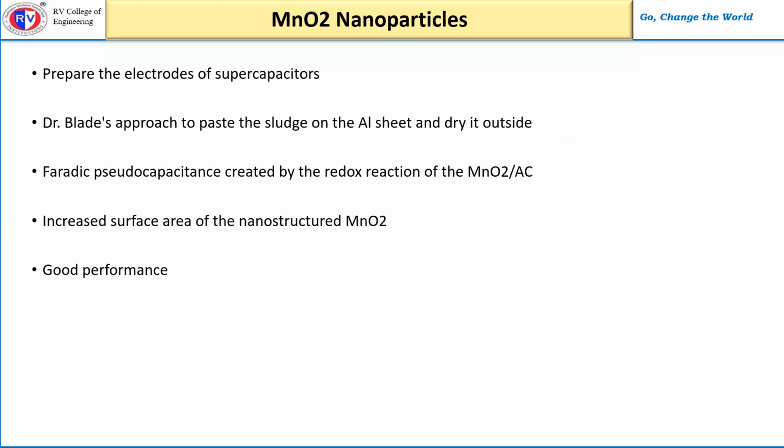Here, two symmetrical manganese oxide and activated carbon composite electrodes were sandwiched between an electrolyte-impregnated polypropylene separator to create the capacitor cells. So before use, electrolyte was pre-wetted onto the electrodes, and several experimental methodologies were used to evaluate the performance of the supercapacitor.